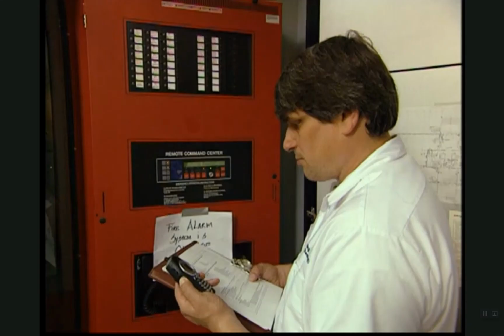Radiant energy detectors must be tested semi-annually. Perform a functional test on the detector following manufacturer's recommendations. Also perform a semi-annual sensitivity test according to the manufacturer's instructions to verify that each radiant energy detector is within its marked and listed sensitivity range.